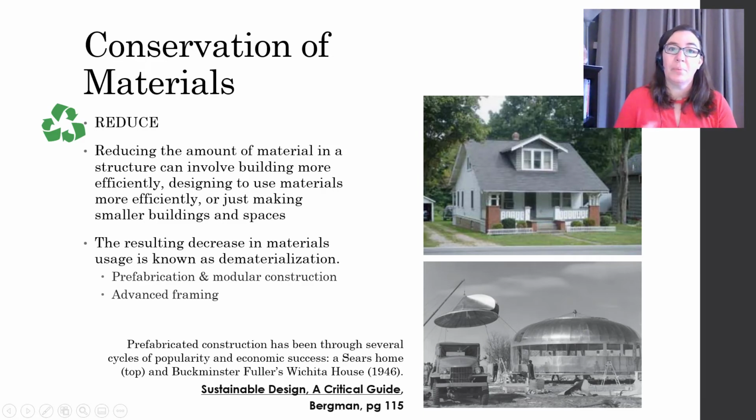You end up with a lot of efficient practices when you're able to do that. Advanced framing is the next tool that is commonly used to reduce materials usage. This is a framing method that carefully details the frame in general to reduce the wood usage, the number of studs, etc.